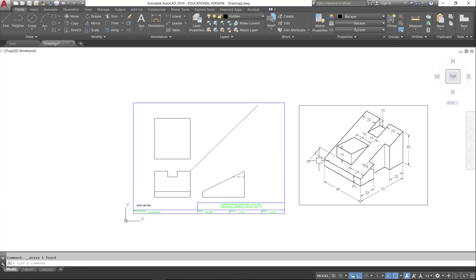Now I can see that it's going up on an angle of 10 millimeters. So I'm going to have to draw a line, and what I'm going to say is perpendicular, P-E-R-P, to that angled surface. So now I know I have a right angle, so I'm going to move that line now. And I can see that it's 10 millimeters up, so I'm just going to offset that 10. It's going to offset parallel. There that bad guy is.